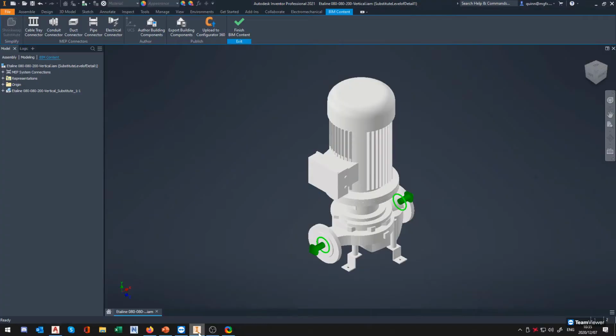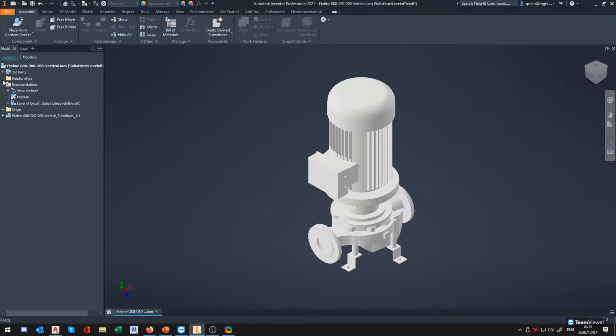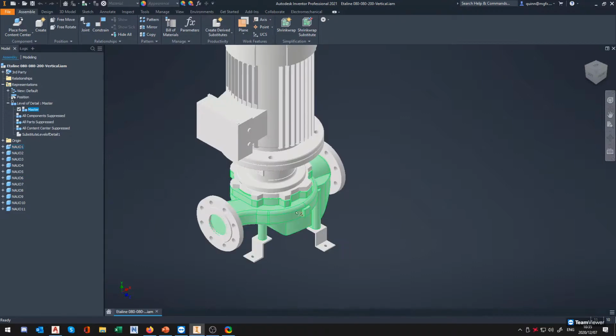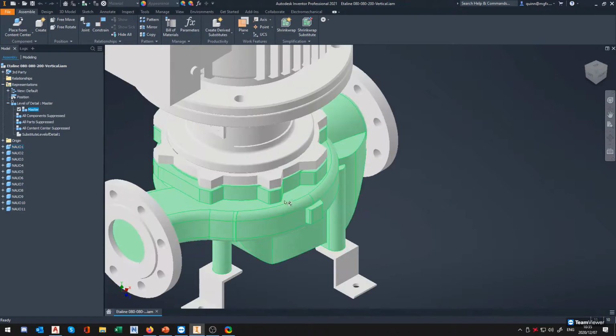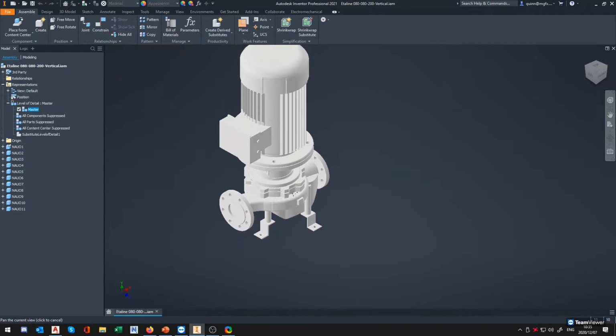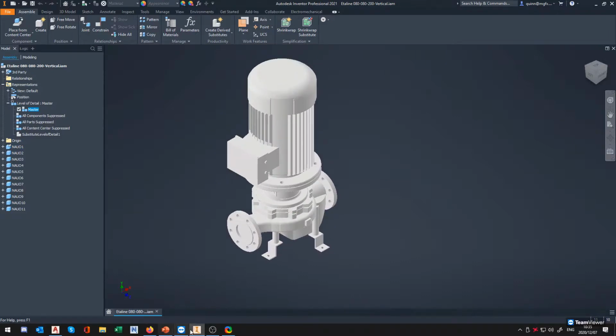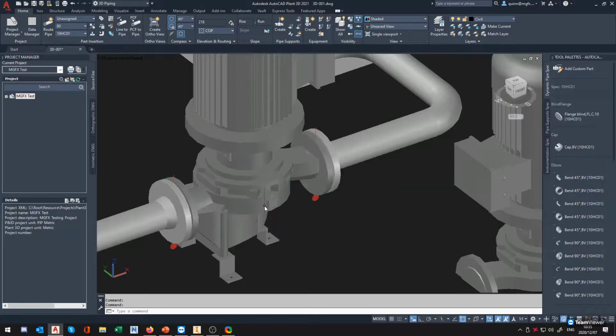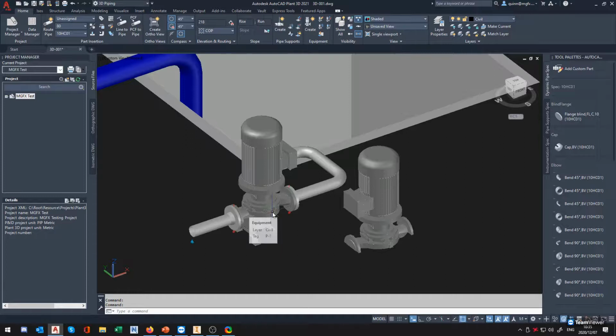If we jump back to our master, it's not including all of the bolt holes, all of the little fillets, chamfers, that type of stuff. It's including the necessary data, but without overdoing it. This is still going to be heavier, don't get me wrong, but it's not going to be as heavy as doing a direct import, or otherwise doing an AutoCAD insert.